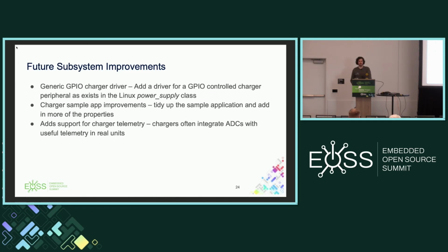outputs that indicate the online status. So it'll be one of those power good outputs, or the output will indicate it's too hot, too cold, or just a generic fault. So in the Linux power supply class, there is a generic GPIO charger driver, and I'd like to see that for Zephyr as well.